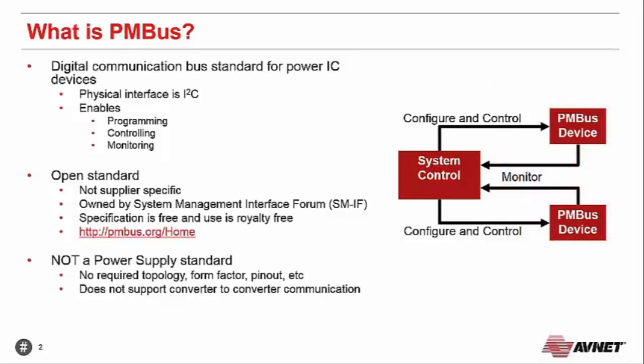It's an open standard, not supplier specific. It's owned by the System Management Interface Forum. The specification is free and it's free to use. You can access it from the web link here. It's important to note that it's not a power supply standard. What I mean by that is it doesn't have a required topology, form factor, pinout, anything like that. It is simply a standard communication interface that can be used with a large variety of different power ICs.